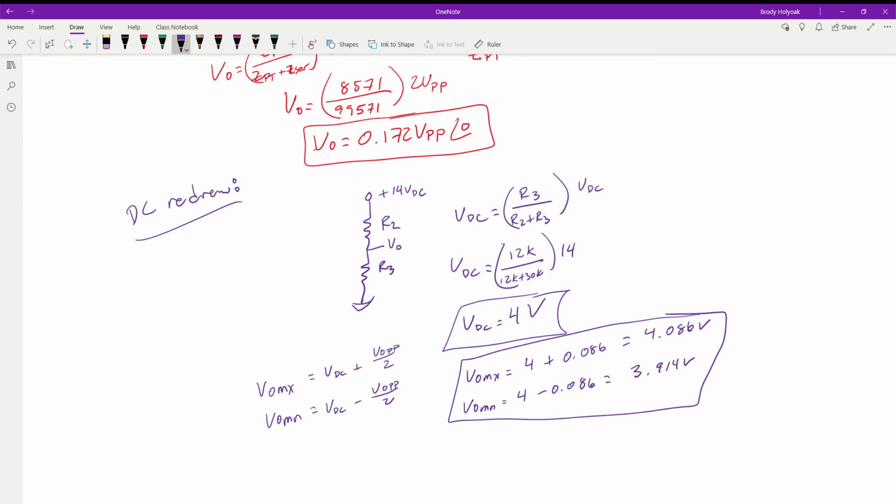That's a huge range. So if we're calculating and we come up with between 4 volts and 3.5 volts, that's not going to matter. That's still well within the range of what the high needs to be. And even then, that's a huge signal loss, considering a 5-volt signal. But the idea is we can get close to these values, and that's going to be good enough.